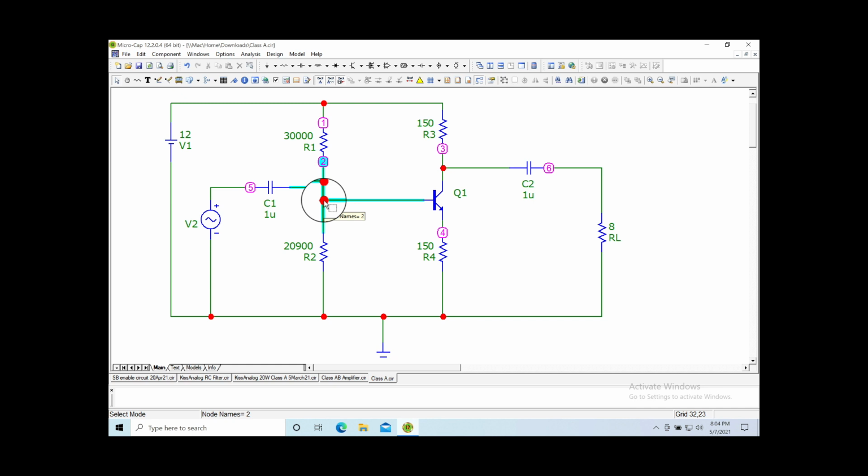But let's look a little further. Now, we have a couple connections here. This capacitor looks like an open for DC, so we don't have to worry about that. But the transistor is not an open. Current will come here and bias the transistor, and go through this resistor to ground. So we really have Q1 base-emitter and R4 in parallel with R2.